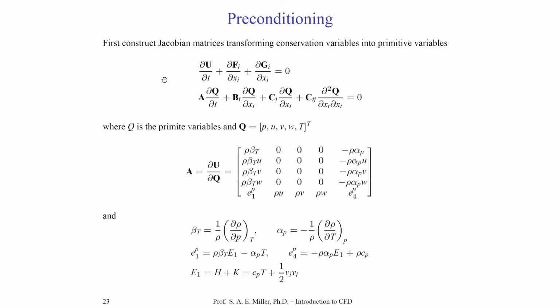As before, we'll rewrite our equations in vector form with Jacobians. So this is perhaps transformed to a curvilinear or transform coordinate system using a finite difference approach. We have a vector u, which is our solution vector of p, the velocities and temperature. F and g, of course, are flux vectors. Here, we'll rewrite A as partial u, partial q, like we've done in the second equation. And q will then be this particular matrix.